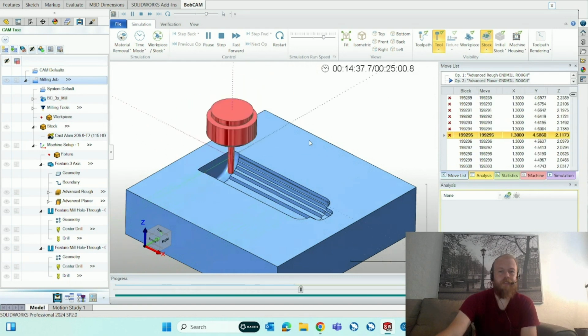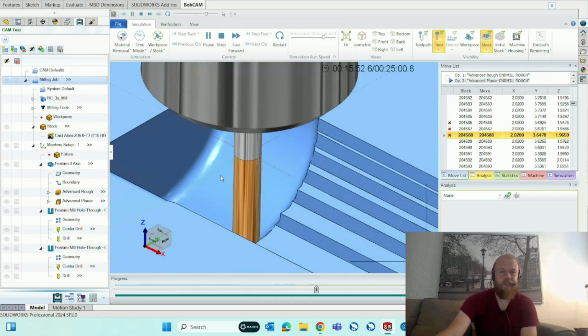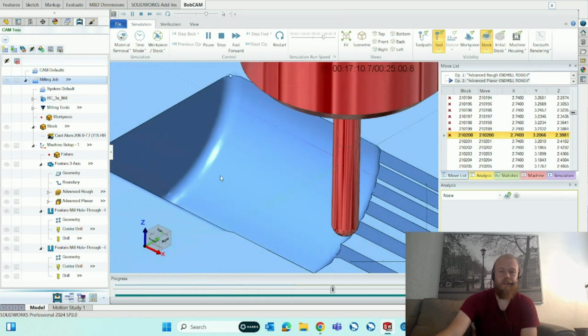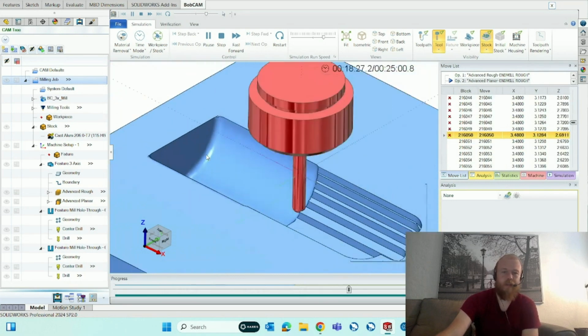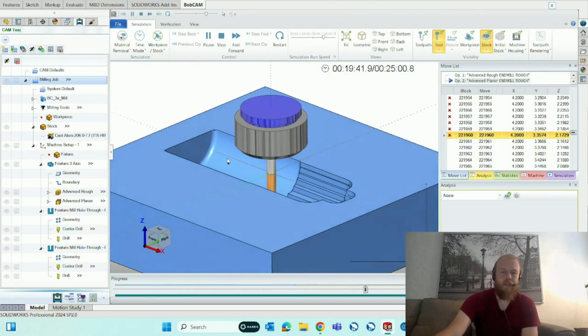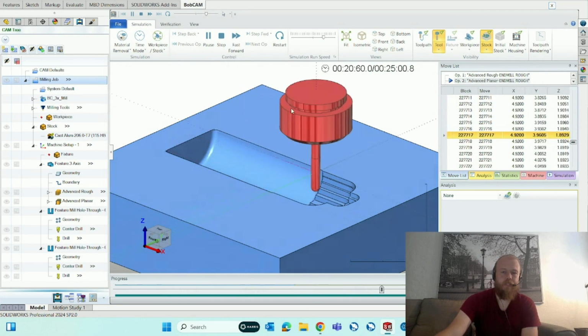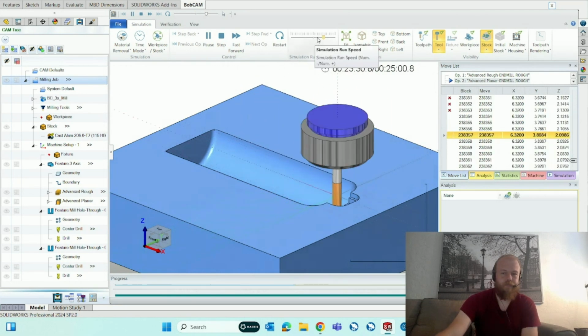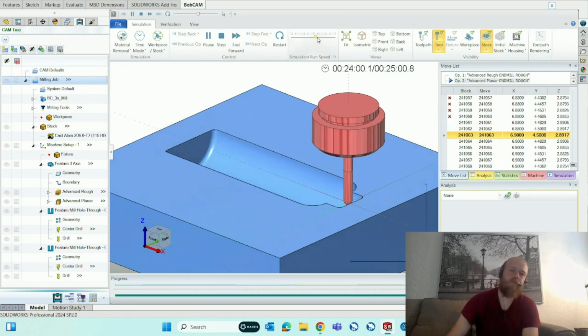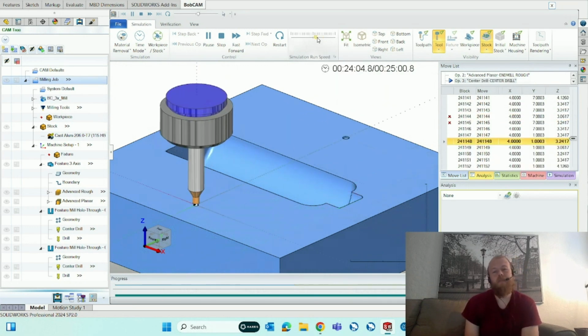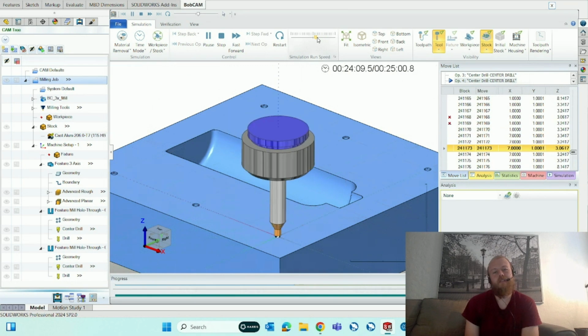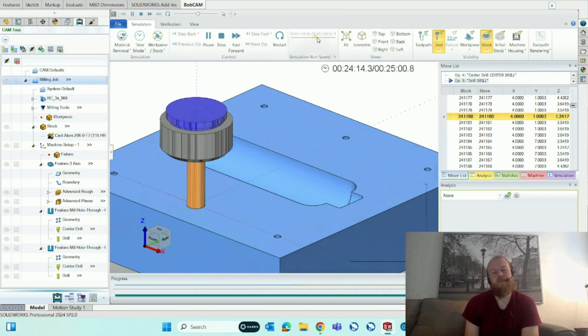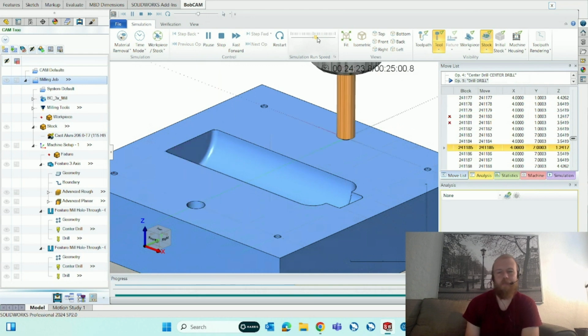So here's the roughing, here's the finish pass, looks a lot cleaner. We'll take a look at it in the verification, the deviation report after this, once we get into the drilling operation here. So I slowed it down a bit. Planar toolpath is done. Does the center drill. Switches to the 1/2 inch drill. And then we'll do the 1/4 inch drill after that.